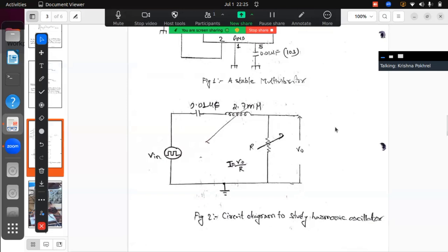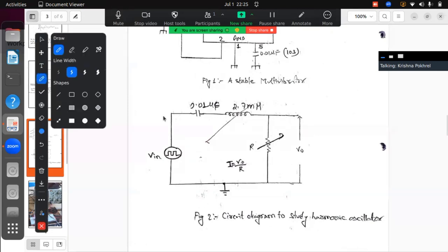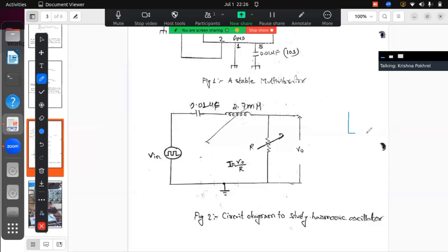For that you can connect a multimeter to this resistance box, with another wire. I want to draw here something, because I have faced this type of problem. This setup is okay, but this is a multimeter. Set the multimeter to DC value, because we are supplying a DC voltage. And what happens is, from here you measure this resistance, not DC, but take it to the resistance measurement area and connect these two wires to the resistance value. And you see whether, when you remove the plug of the resistance, there should be a value reading, because I found this type of error in this device.